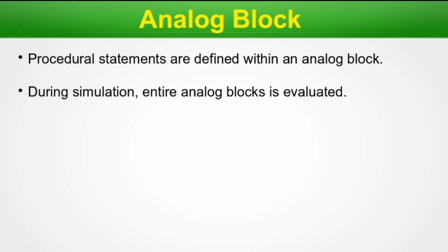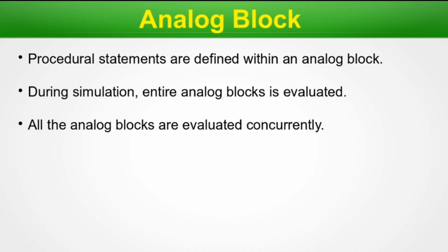During simulation, the entire analog block is evaluated. All the analog blocks are evaluated concurrently. So, say in our code there is more than one analog block, they will be evaluated concurrently, even though they may be at the beginning or the end, that is not their sequence. Any number of analog blocks in our Verilog-A code will be evaluated concurrently.